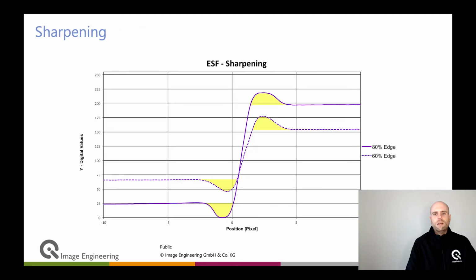Okay, if we have measured the edge spread function in great detail, we can also use that to measure the undershoot and overshoot. I drew the real camera on the other slide without any kind of sharpening. But in reality, with many devices like mobile phones and security cameras, everywhere where you have some sharpening applied, your edge spread function might look like this, where you have a strong overshoot and undershoot, or ringing artifacts. These can be disturbing depending on size and amount, and this is definitely something that you want to measure and track in your development phase.